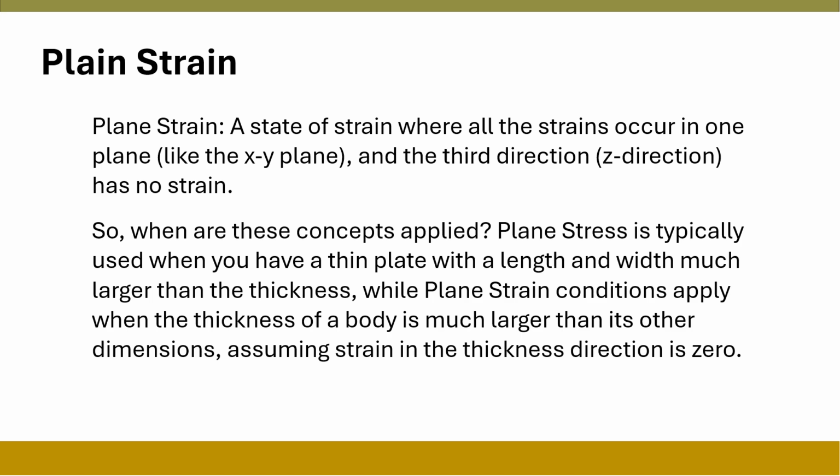So, when are these concepts applied? Plane stress is typically used when you have a thin plate with a length and width much larger than the thickness, while plane strain conditions apply when the thickness of a body is much larger than its other dimensions, assuming strain in the thickness direction is zero.